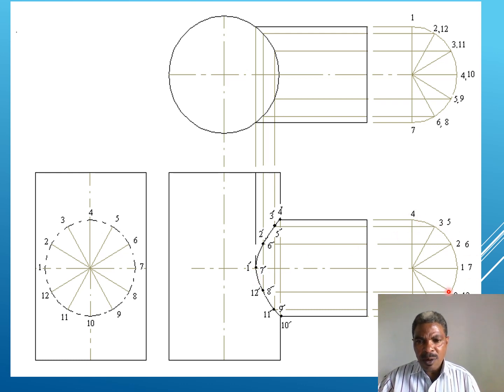From the semicircle, which is laid on the front view, we have to project these labeled numbers, 4, until it meets the 4 in our plan view. As you can see, 4 is here. If we project downwards here, it would meet here. This is our first point. Likewise for 10. 10 from the same point, projected downwards, meets another 10 here.